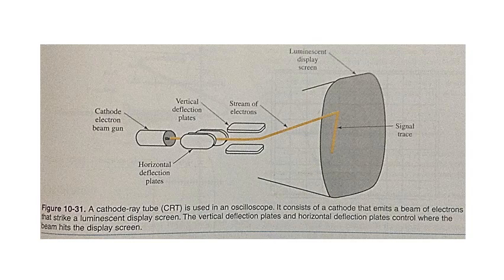If horizontal sweep were set at 120 Hz, which is twice as fast as the 60 Hz input signal, then two complete waves would appear on the screen. The horizontal frequency can be adjusted so that the waveforms appear stationary, or not moving.